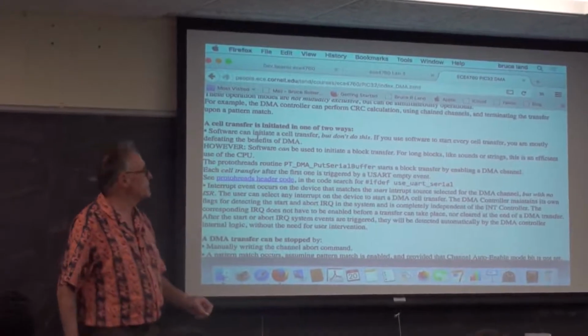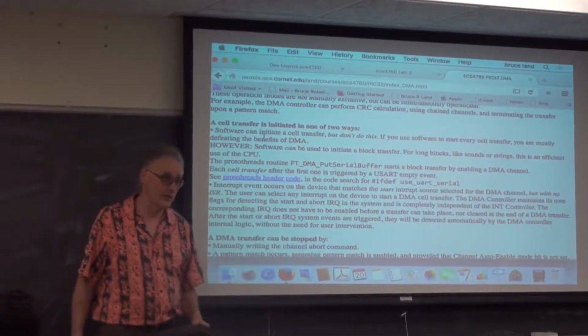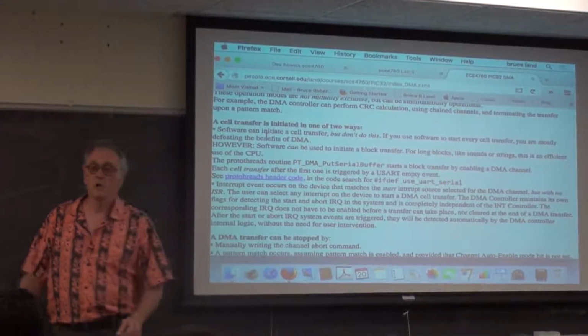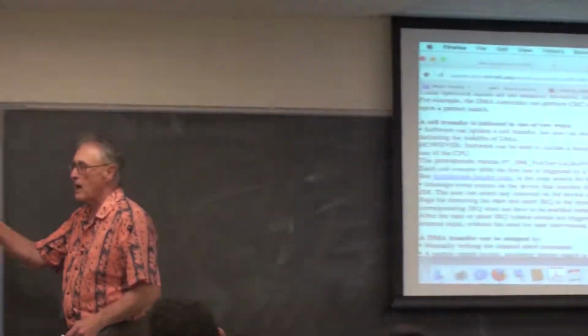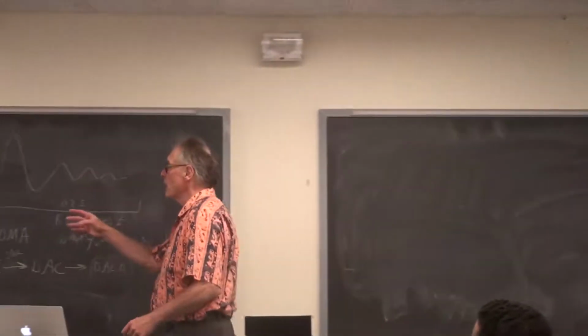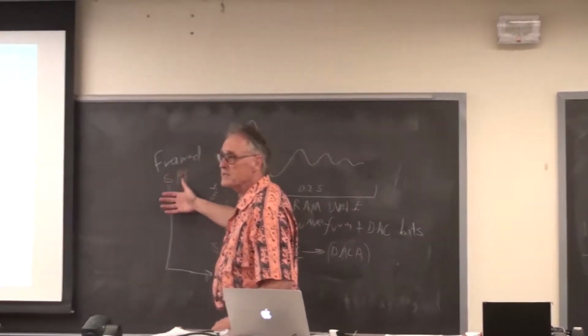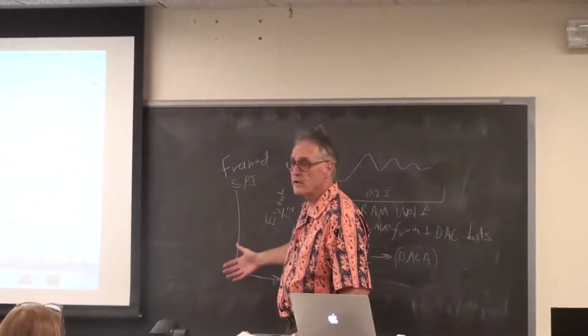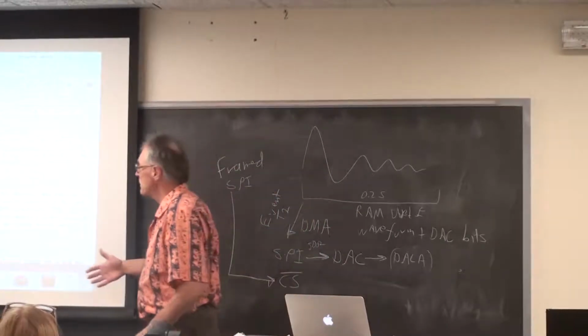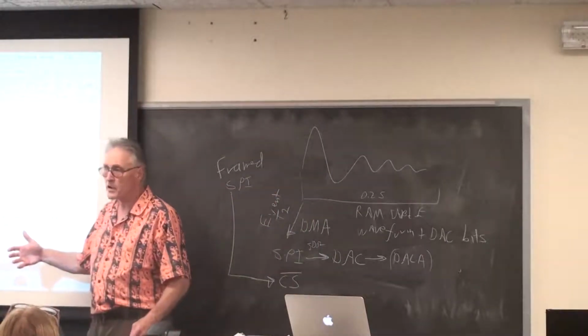However, you can use software to initiate a block transfer. So software is going to enable the block or set up a block and then go do something else, and for the next 0.1 seconds, 10 seconds, however long the transfer lasts, the DMA channel will run by itself with no software interaction.